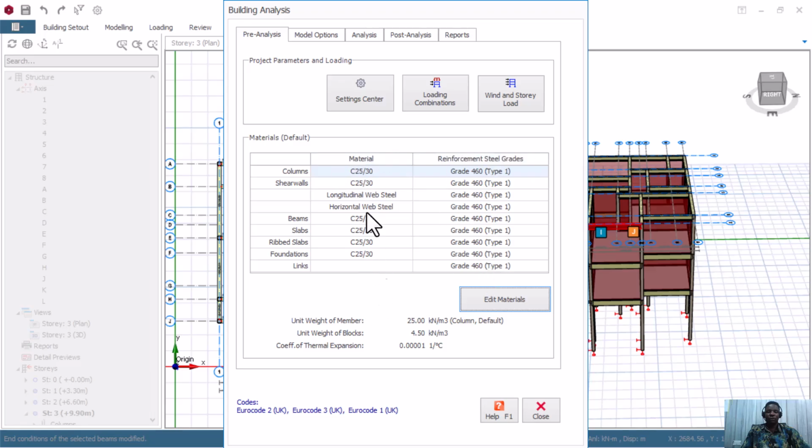So either of the rebars we pick is going to be designed with this grade, either the 12 or the 10 mm and all of that. You're going to use this particular grade to design for the size of those rebars. Okay, in that we're not designing for the wind because we have a little situation here. But if you still want to consider designing for the wind, then you can activate that. But we want to keep this video as simple as that.